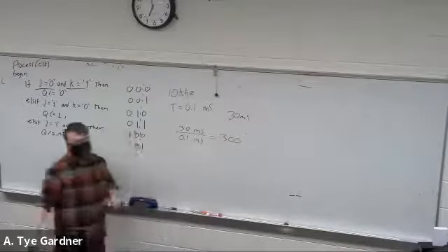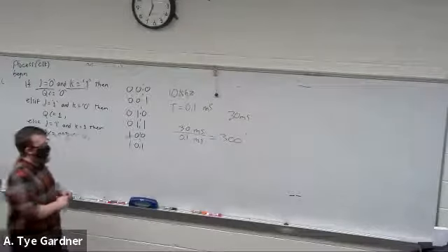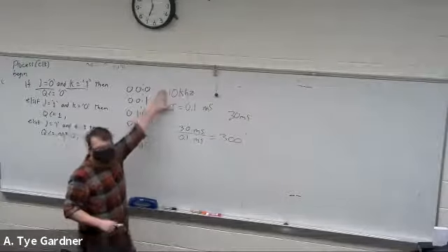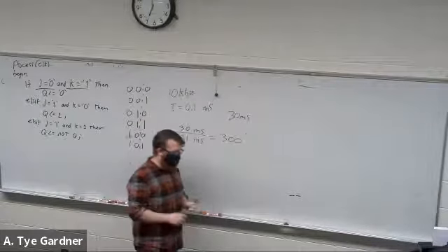So there we go. Time to clocks. That's how we do that conversion. It's an important conversion because digital circuits don't know what time is. It is your job to be able to take their language of hertz, clocks, and turn it to actual time.